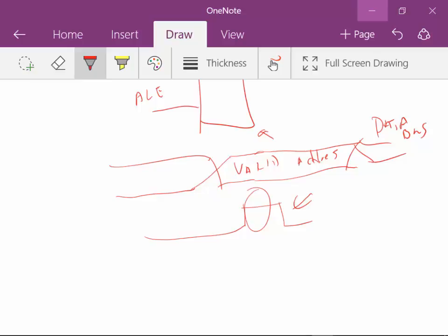That there, we share the lines. They're multiplexed. Some of the time they're address lines. Some of the time they're data lines. That's used in a lot of different applications. This is the simplest one. So we use the D latches for that. They're not necessarily called D latches when we look at an address latch. They're just called an address latch. But what's internal is 8 D latches, and they're gated. In the case of an address latch, they're usually not clocked. But at this point, this tells it to latch the data, and this tells it to just hold the data. And then the data is free to change however it wants on the lines.